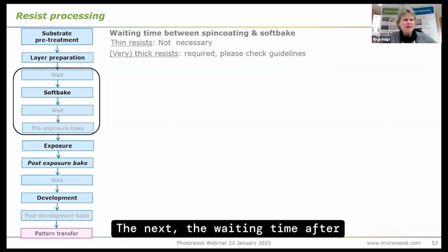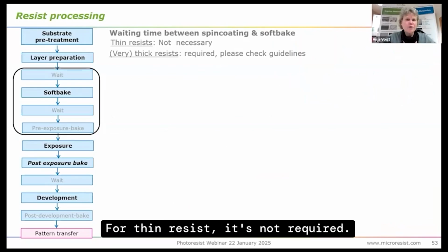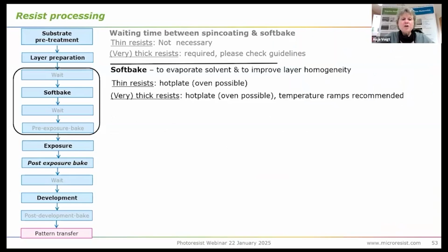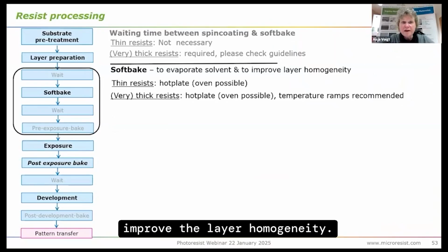The waiting time after layer preparation: for thin resist, it's not required. For thick, it might be required. Check the guideline. Soft bake. Why? To evaporate the solvent and to improve the layer homogeneity.